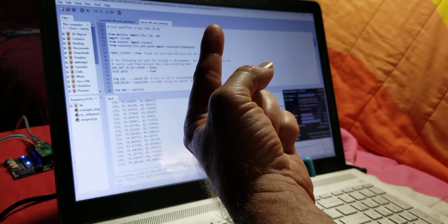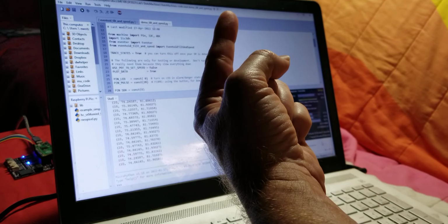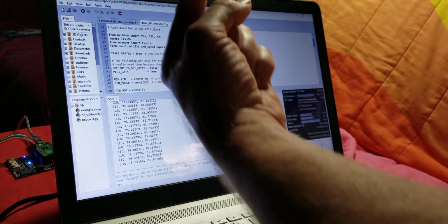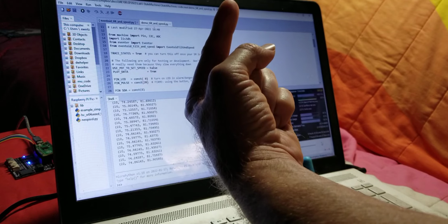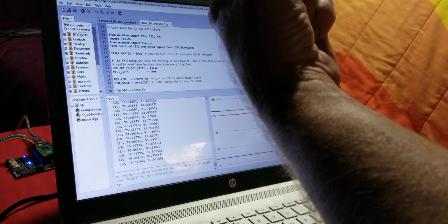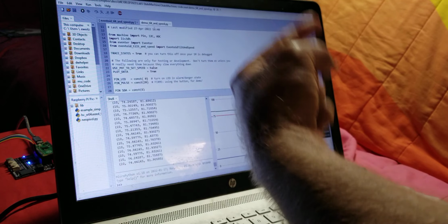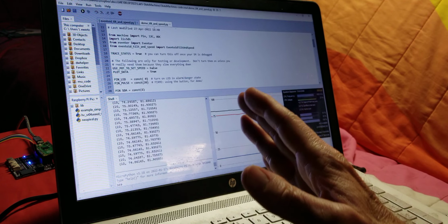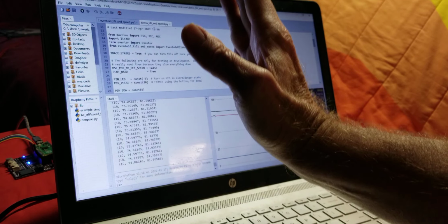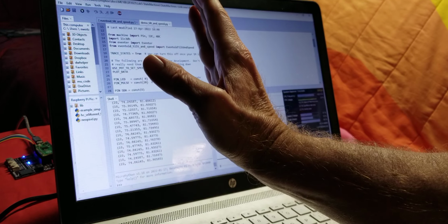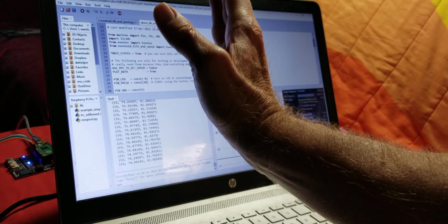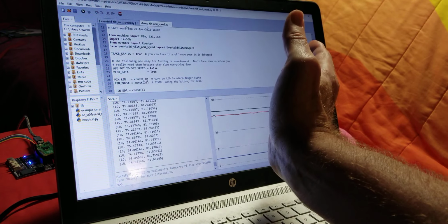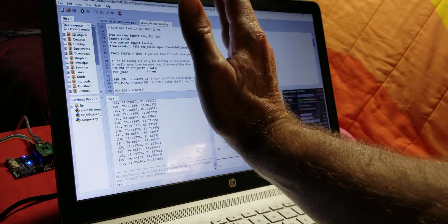And the reason why I chose 90 miles per hour as the max and 90 degrees vertical this way is, my goodness, my safety rules are going to be: as long as your speed doesn't exceed the degree angle of the tilt of the accelerometer, you're operating in a safe region. So if your tilt is 90, you can go up to 90 miles per hour. If your tilt is any less than 90, that's a danger condition because your speed is exceeding your angle, where your angle goes from 0 this way to 90 this way.